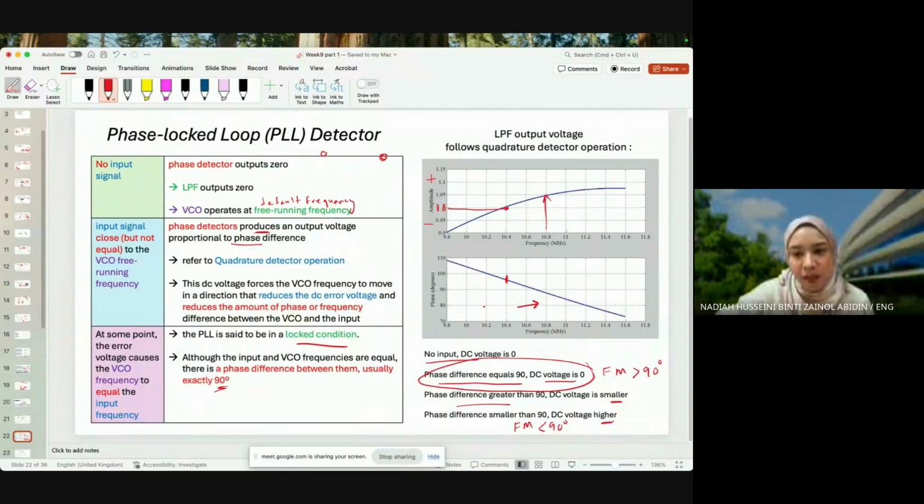If the frequency decreases, you would get a low voltage, right? But for the VCO, the amplitude here should not be used. Instead, the reference should start at 0, with positive values on one side and negative values on the other, because this is how the VCO is tuned. The VCO is tuned from 0 to positive voltage, and 0 to negative voltage.